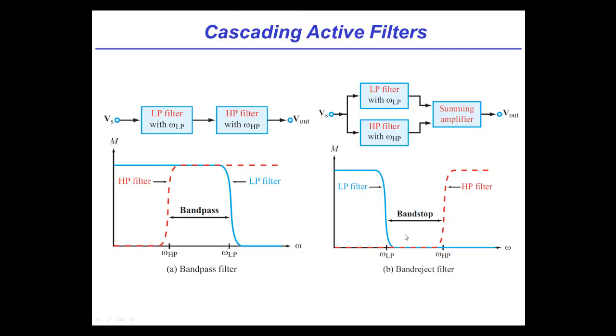Now, Michelle, I have a thought. You have a thought? Yes, and my thought is the following. Given that each of these is contributing, assuming these are first order terms, a 20 dB per decade slope on its edge, could you do something to get steeper filters?